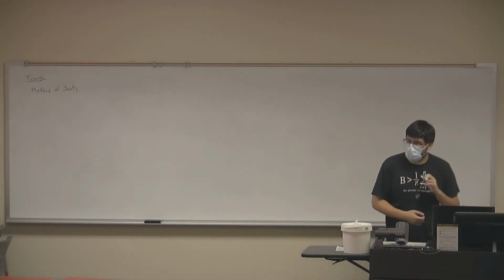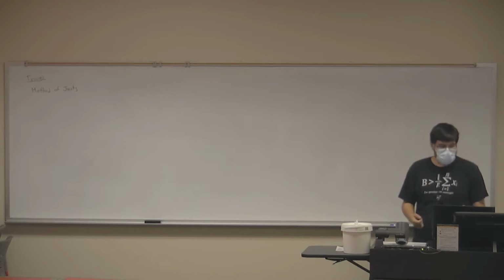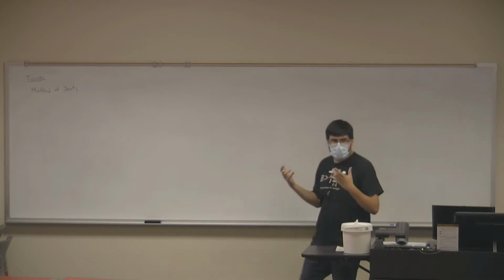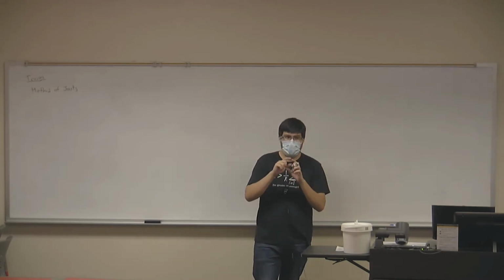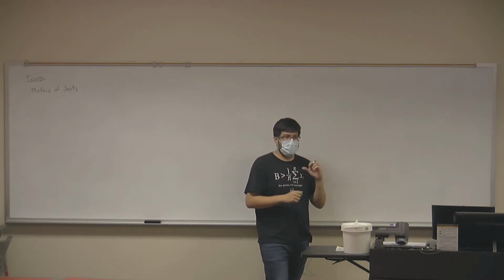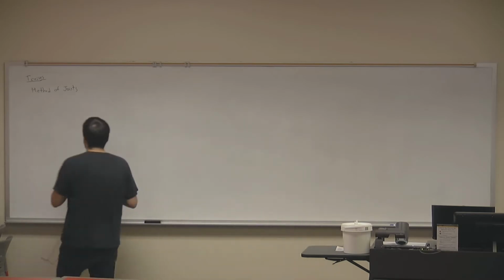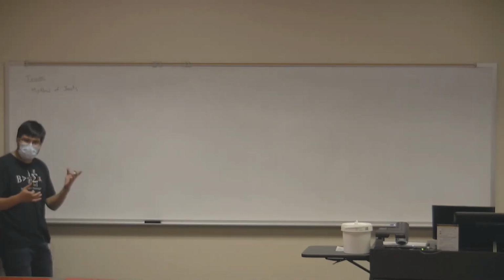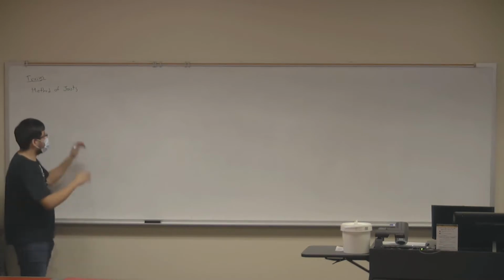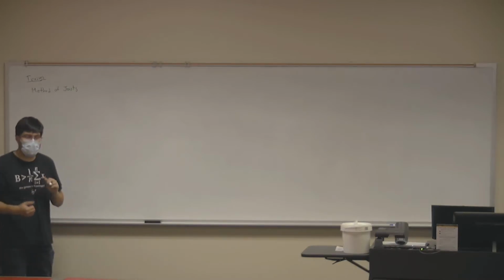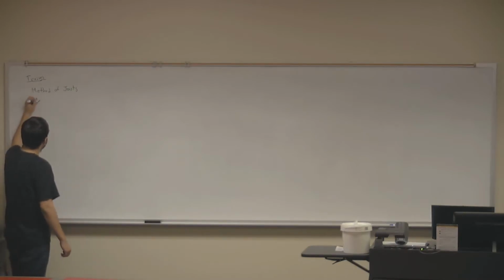Now, there's another thing that we said last week. In addition to looking at each joint individually, you can actually look at your structure as a whole. You can look at that combination of trusses as one body, and you can do that to find the reactions, right? So today we're going to look at one method that kind of combines the big picture, little picture approaches, and that's going to be called the method of sections.